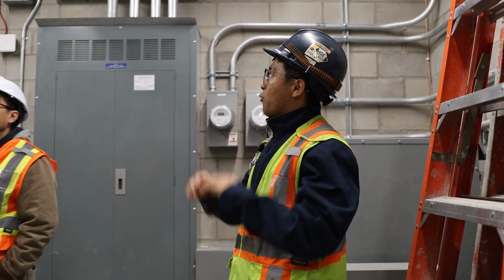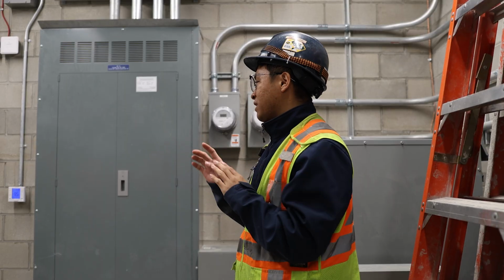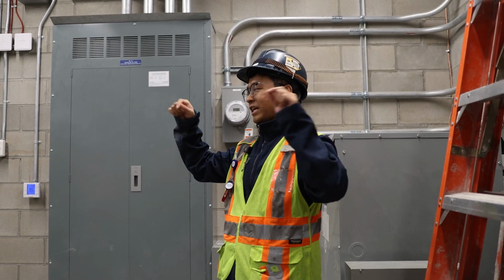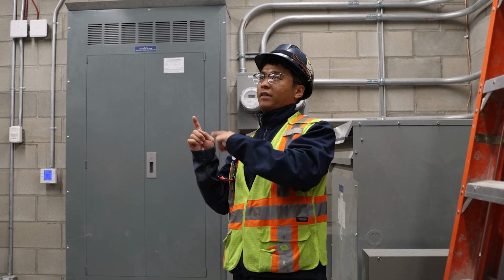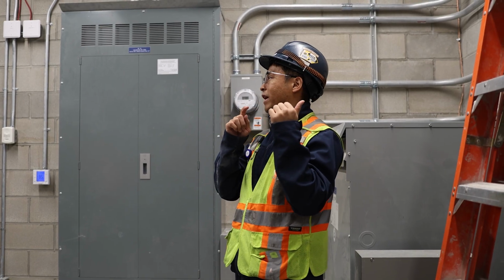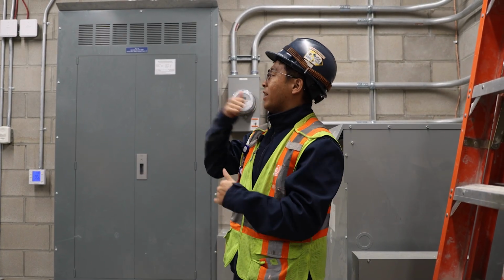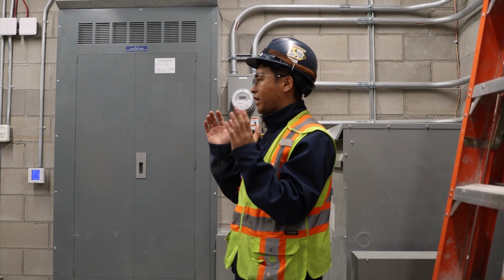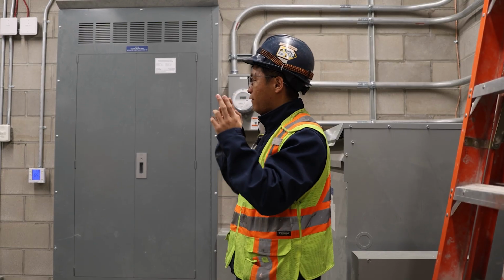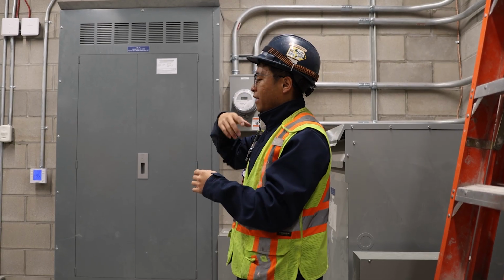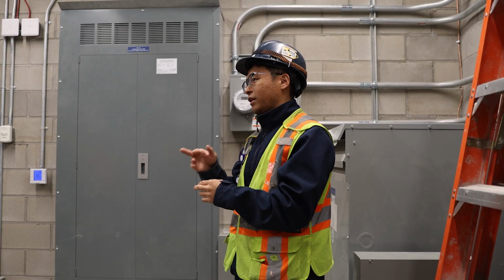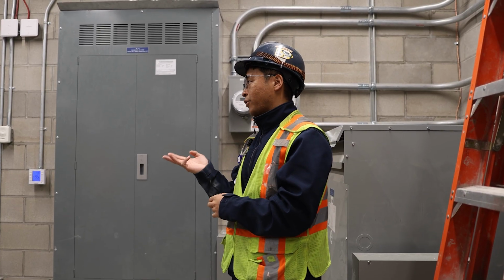What we do is, when the heat pump is running in the winter season, it provides heat to the room, and the other side of the heat pump will be cold. It will require heat, and then we will open the heating pipe isolation valve, and the pump will turn on. The 3-way valve will modulate to maintain the loop temperature at 30 degrees C.